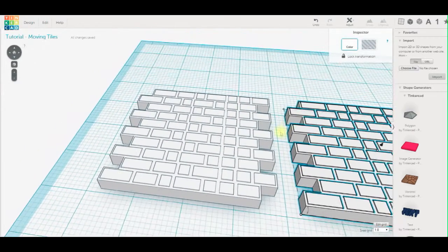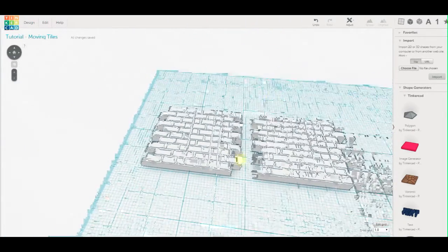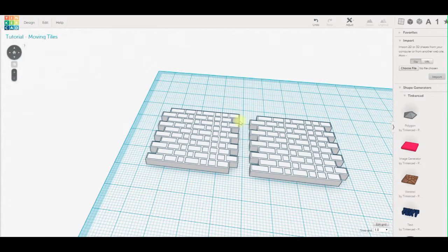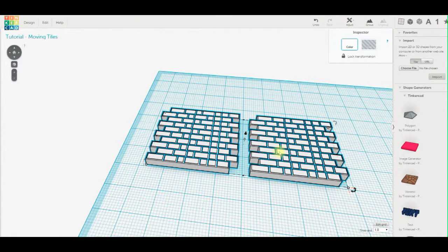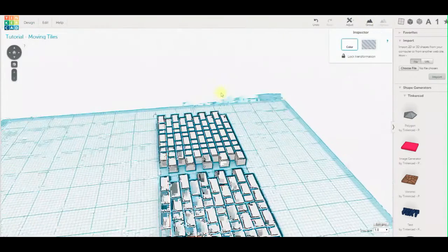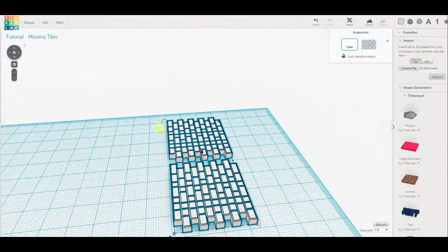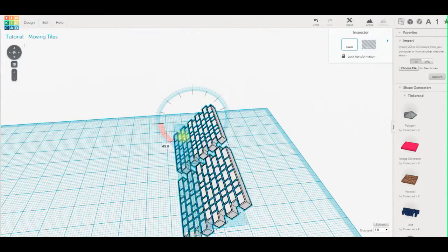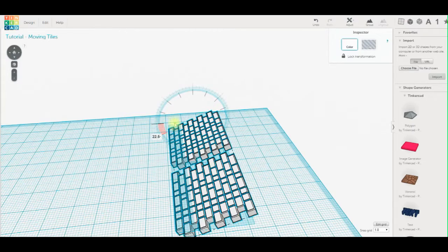Okay, you can also manipulate parts in groups, so you don't have to just spin both of them. If you wanted to twist them both, you can click and drag around the two parts. You can either group them together so they become one object, which you can ungroup later, or while they're still selected, you can still slide around the part and you can manipulate both at once.